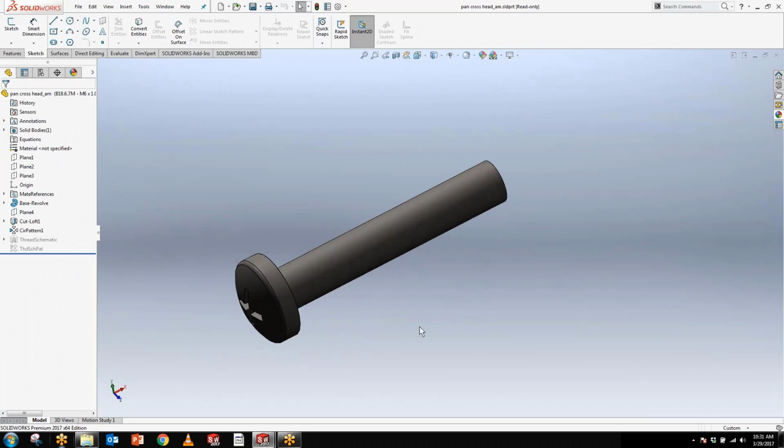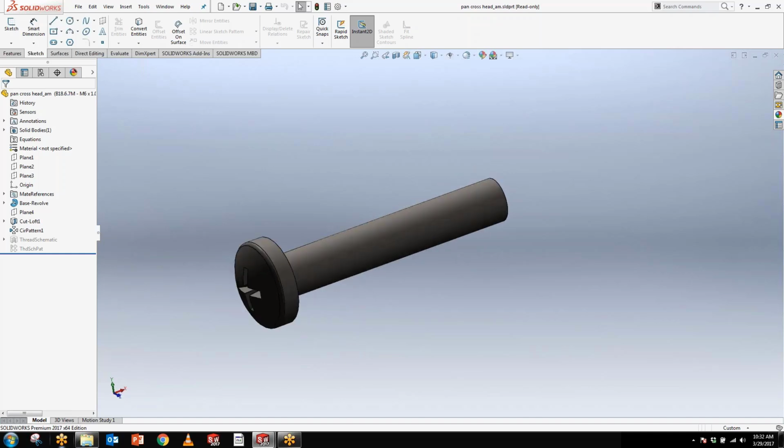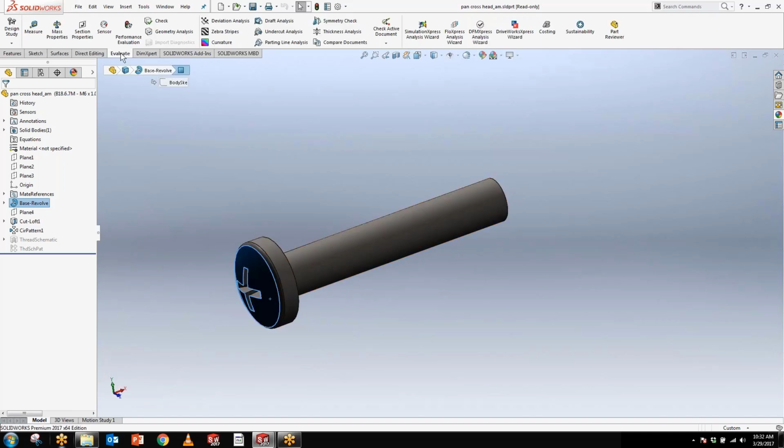Like the example that we saw before, guys, in the second topic I talked about, where we had to examine and suppress unneeded features. My evaluation in that list showed that this part is going to take the longest time to rebuild. So I opened it up individually. What if I want to make changes here to take less time, evaluate it and see how it performs, and go from there.